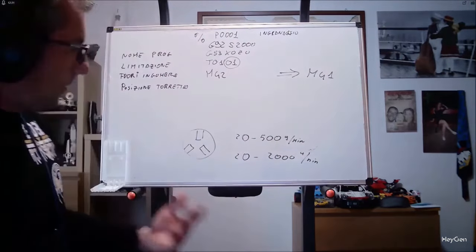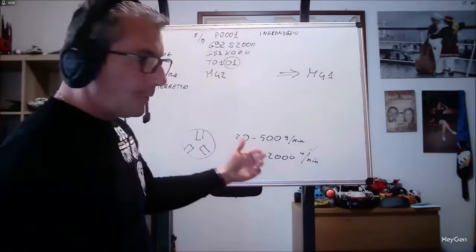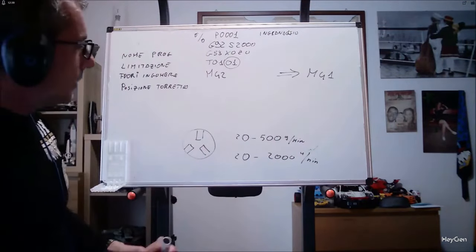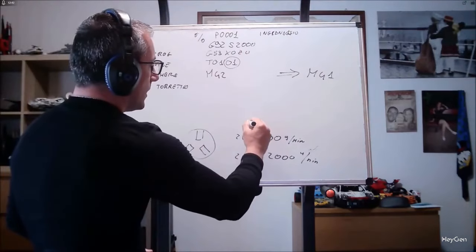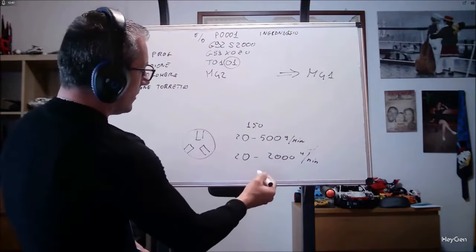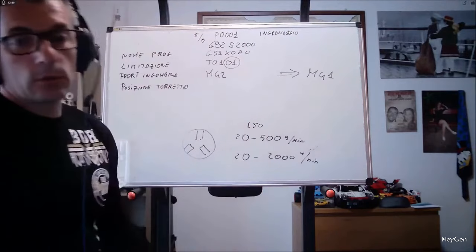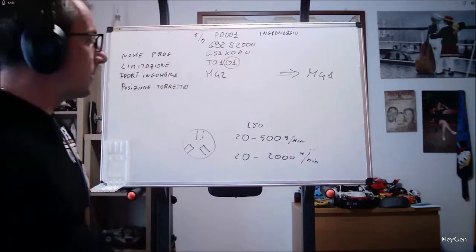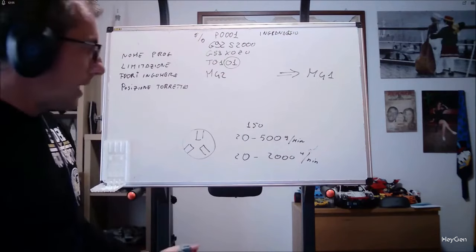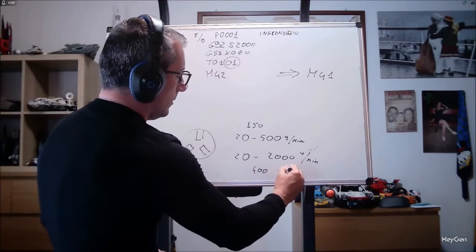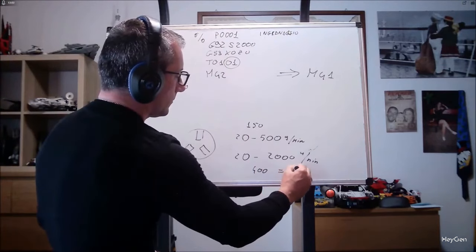No, it changes the way torque is developed, so the motor's power. If you need to do, for example, range 1 at 150 RPM, it will provide all the available torque. Range 2 at 150 RPM, I'm not saying you can stop it with a finger, but if you are already doing a heavy cut, the machine will probably stop. So range 2 is recommended between 400 and the maximum RPM.